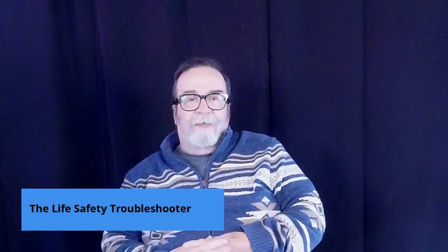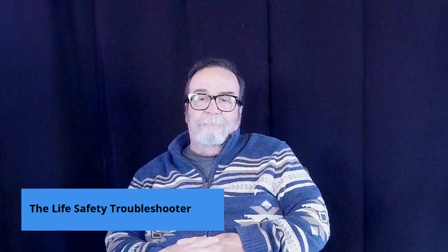What I'd like to talk about in this episode is the dreaded invalid replies with no set pattern. They get to be a little irritating, and the reason they have no set pattern is that what's causing these invalid replies is normally a device causing intermittent shorts at different potentials. So it's not a dead short, it's more of a floating short. Sometimes it'll go up, down, middle, but there's a way to find this. There's a couple of ways that you can actually find this.